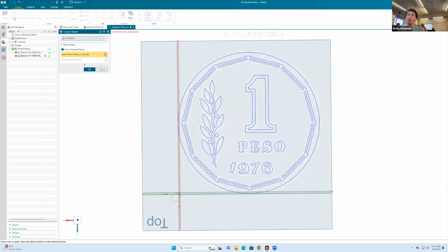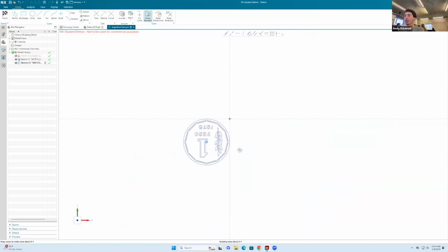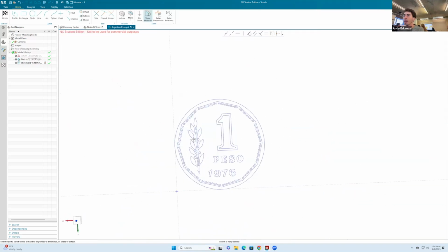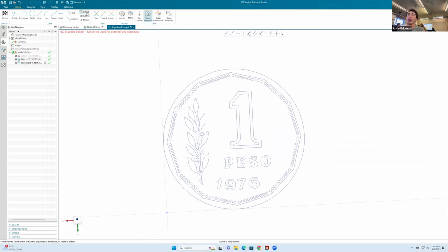In fact, I'm going to create a new sketch in the exact same plane, which is the top plane, just like that. And I'm going to use a command in Fusion called project. So what does project do? It's exactly what the name means. You click project, and here I'm clicking where it says single curve instead of infer curve. I click on that circle and say okay.